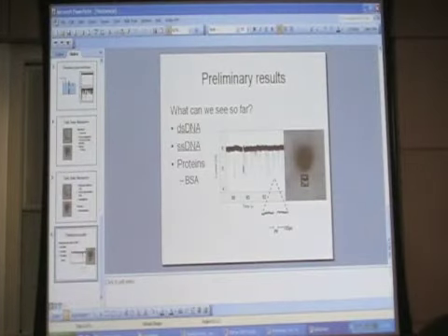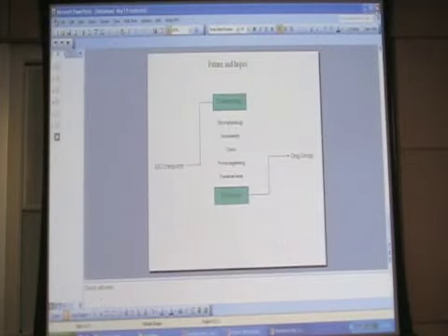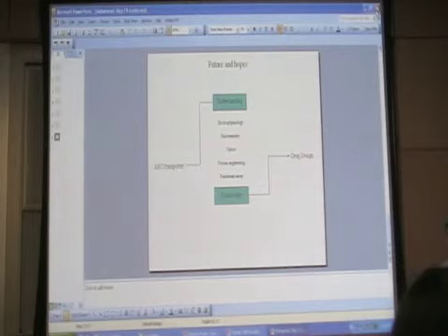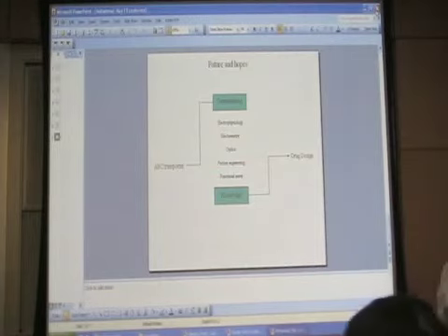Why do you use silicon nitride? Well, we make windows of silicon nitride that are 30 nanometers thick. It's convenient to do so. We put them on a silicon substrate, grow them, and then take away the bottom silicon. We have a nice 30 nanometer thick window, so we drill it with an electron microscope. It's convenient, that's it.